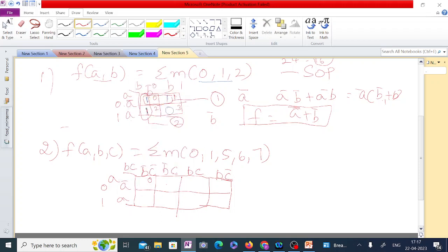As you all know, we follow the gray code technique here because at each and every consecutive location, you need to ensure that there is a 1-bit change. If you write BC bar here, it is not consistent. So I have put BC here. So this is the gray code format which we have already discussed. So I think that is clear for you all. So in that case, this location becomes 3 and this becomes 2 and this is 4, 5, 7 and 6.